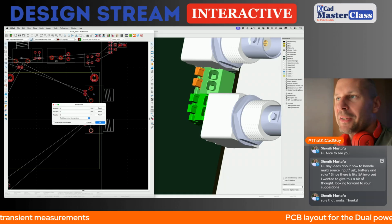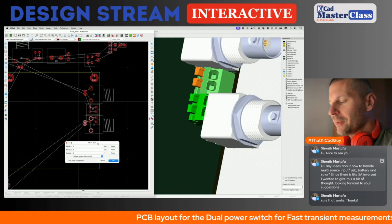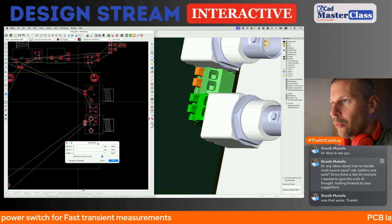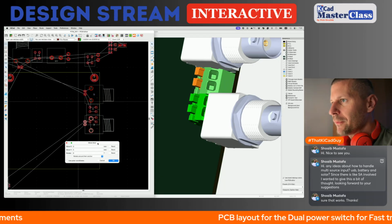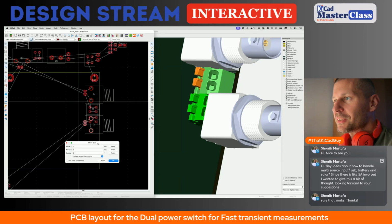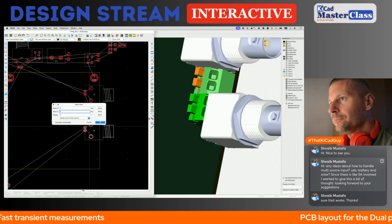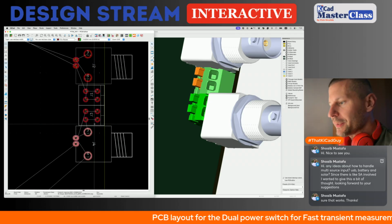The reason why I don't use my favorite feature, where I hit the M key for move, then press the cursor key down, and then use my mouse because the vertical axis is locked, is that this feature doesn't work in KiCad 9.0.5.